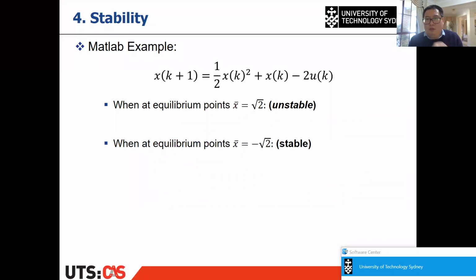So what I want to introduce here is, even at an equilibrium point, you can still say it is stable or not. I give an example about the inverted pendulum. In that case, it is at equilibrium because if you don't give any input, it will never change the state, right? But any change of the state will make it change a lot, will make it fall. So it is the equilibrium point, but it is not stable, right? So that is what it means.